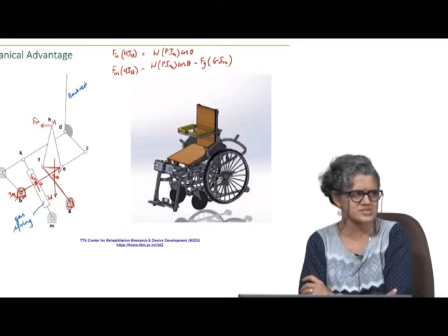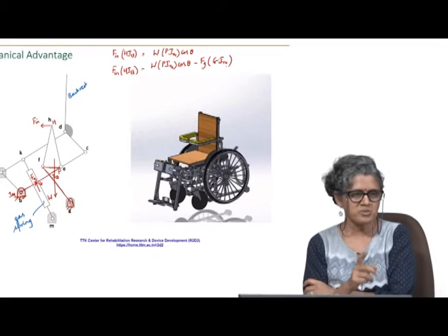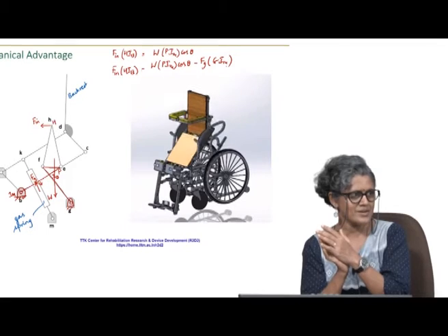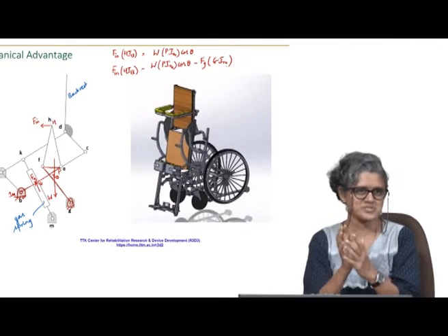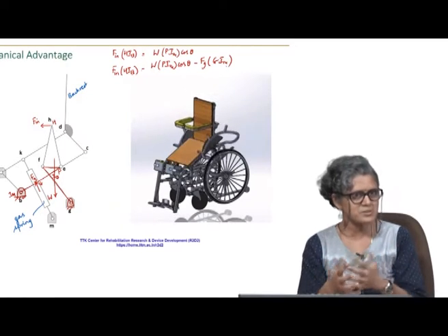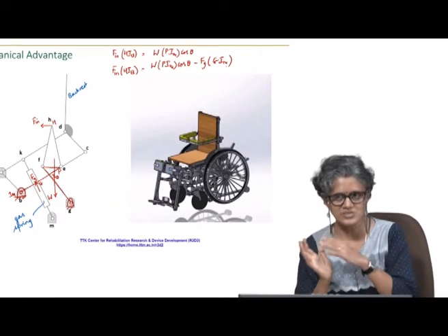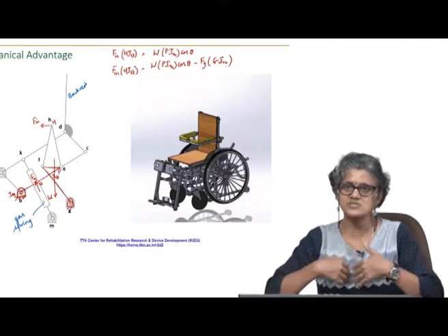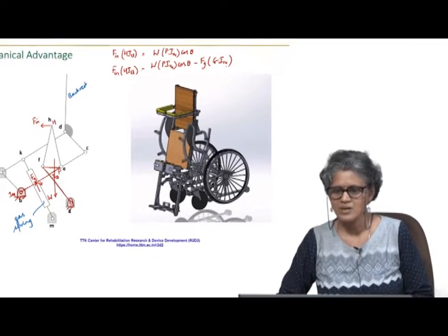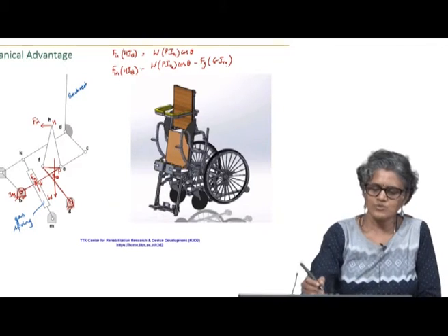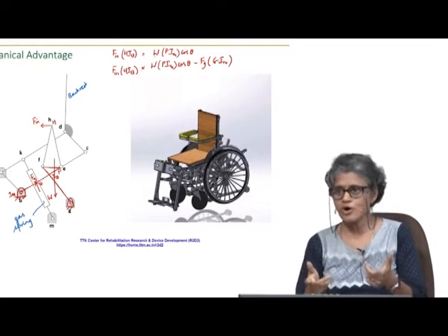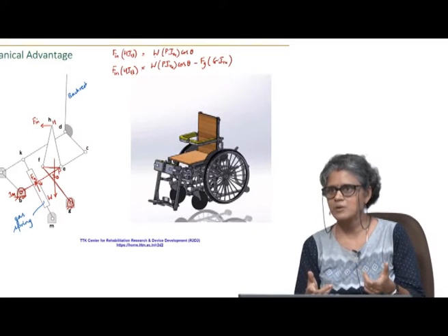Okay. You could use the first design that we used, a compression spring or an extension spring, but the problem with that is when the person goes up, it just jumps because there is no damping present in that. So, a gas spring is better because of its damping characteristics. So, it is gradual, it does not just throw the person up like that. Okay. So, use of this can reduce the input torque that you require.